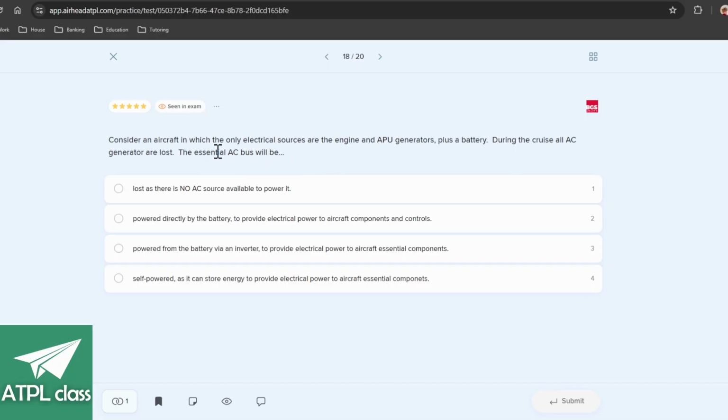This is quite a mean question if you're not used to... So, I'm getting ahead of myself. It's quite a mean question because this is all knowledge about buses and AC essential and DC essential. And that becomes very good working knowledge once you are flying a big jet. But when you're not even flying these jets and you're not really sure what AC buses are and when you use them, it's quite tricky to know when the AC essential bus will be powered. Because you don't even know what an AC essential bus is.